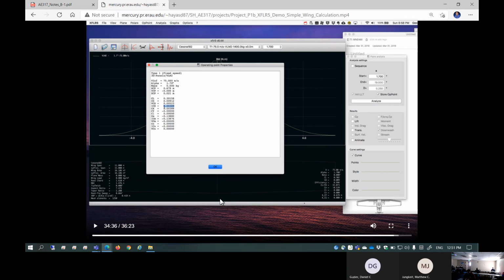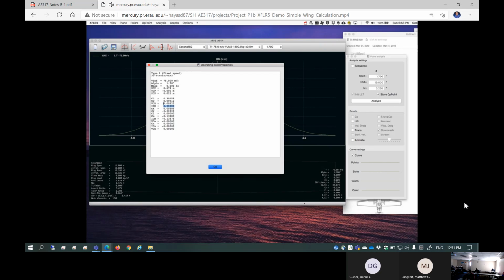Suppose this is an operating point of an airplane for cruising condition, takeoff condition, landing condition. You can set out of those operating points, you can squeeze out point-wise data for the detailed CD, CM, CL, other things. Okay, so this is the operating data point you can store. Stands for induced, viscous, total, and lift coefficient. So those are key numbers right here. It doesn't report the max bending moment here, which would actually be nice.